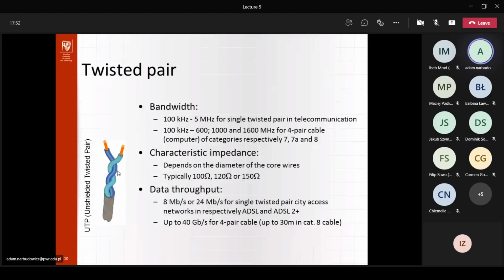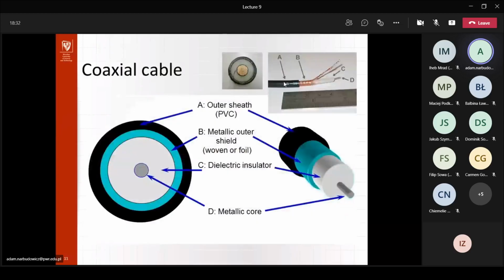So we have the same amount of distortion on the two wires, the same electric field induced, which means if we just take the differential signal, we can simply get rid of the common signal and part of that interference. And basically the twisting of the cables around each other helps. So it's definitely a better case than putting them just parallel without twisting. However, well, you can see that it's really not great, right? So still that's not necessarily the best choice.